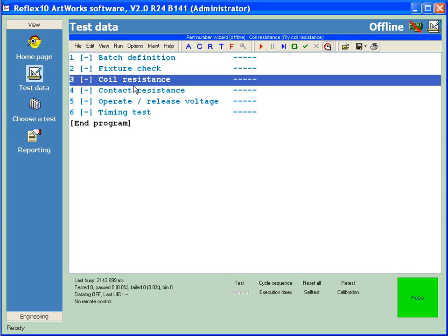Now the benefit of this is that if you've got maybe 20 devices, all of which are only slightly different to one another electrically, those electrical differences can be encoded in the part number list, and you can use just one single test program to handle the electrical test order of each of the test sequences. And this makes maintenance of the test programs much easier than trying to keep 20 test programs up to date and in track with one another. Here you can modify the one test program, and that change will apply to all of the part numbers that are based on that program.